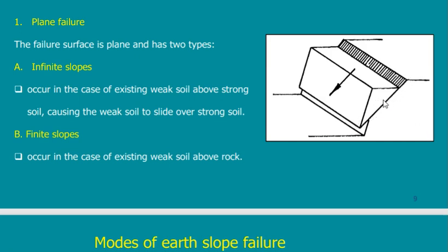So I calculate the load of this wedge and I compare it to the friction at this wedge, and I calculate a number, and then study another case, go a little bit below. The value of the load will increase. And the value also of the stress, the shearing stress that will carry the load, will increase also. So I will check this case and I will check this case and we'll see which one is the critical.